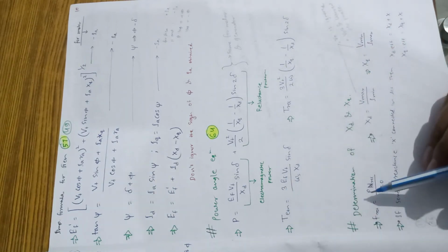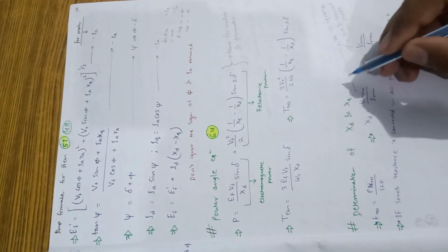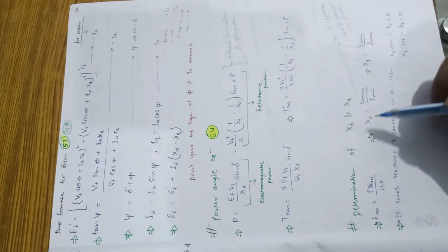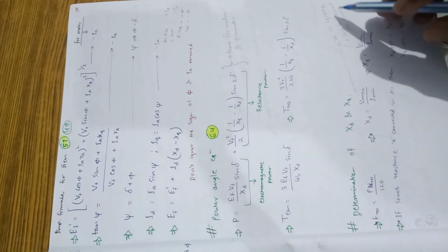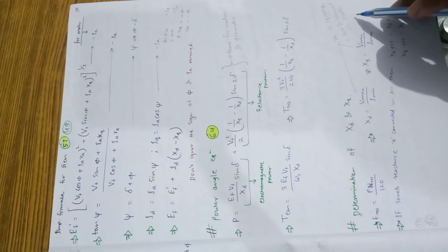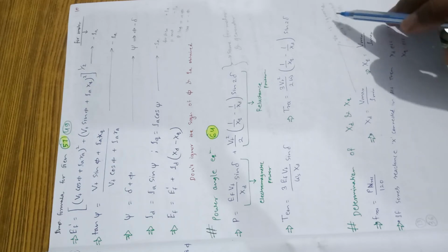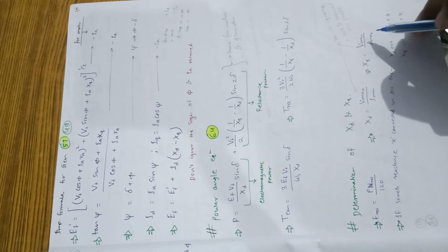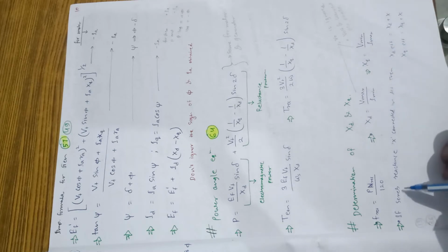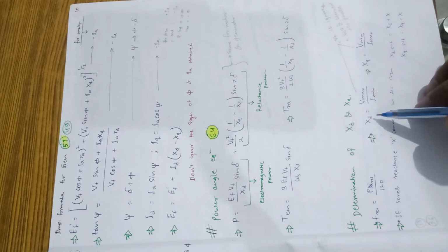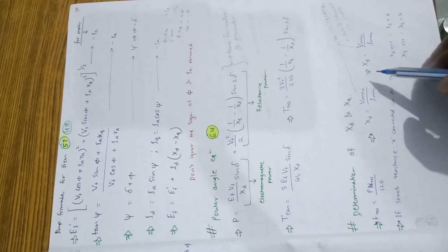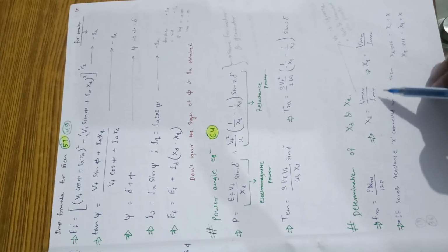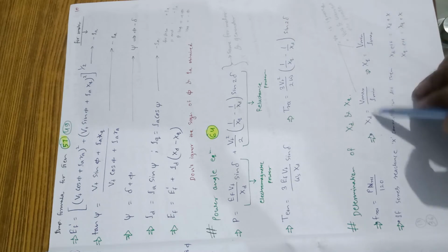Okay, so determination of xd and xq is done by using the slip test. Here we are not studying too much about the slip test, but remember the most important thing, that when Ra is ignored and voltage and current are per phase, we write xd is equal to Vmax upon I min, and xq is equal to Vmin upon I max. We know that xd is greater than xq. With that concept also we can make out that when we do Vmax upon I min, then we'll get the maximum value. So this is the logic to remember.